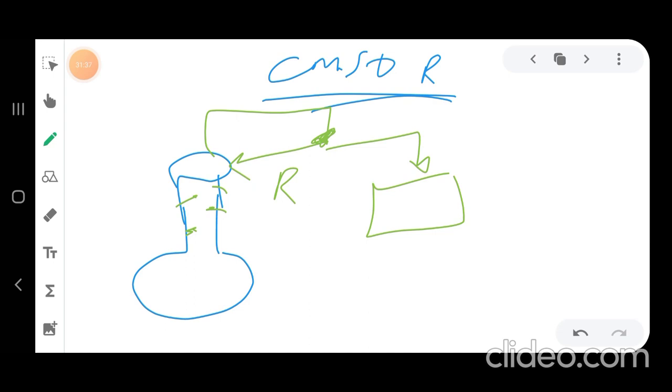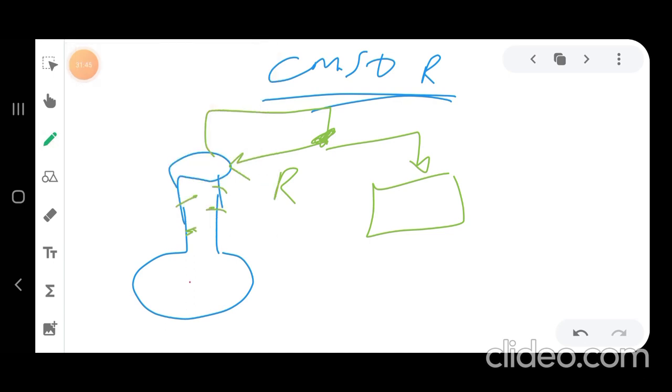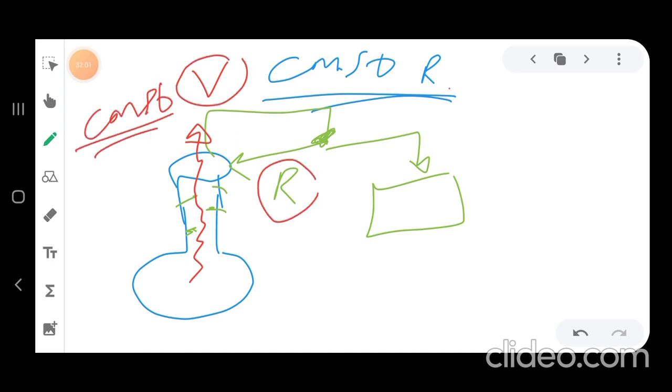We are going to assume that the vapor leaving the system, let's call it V, which is called the boil up, is constant. And you know that R is constant for this type, and R is just L over D, right? D is the distillate, and L is the liquid returning to the still pot. And you know that from material balance V is equal to D plus L.